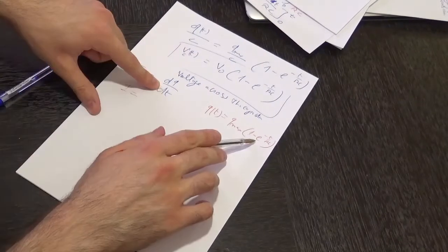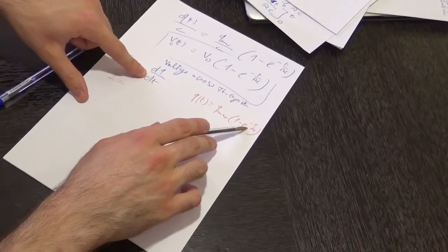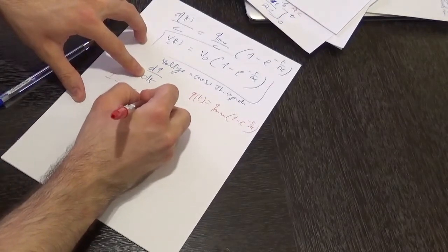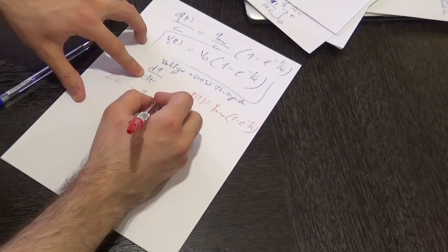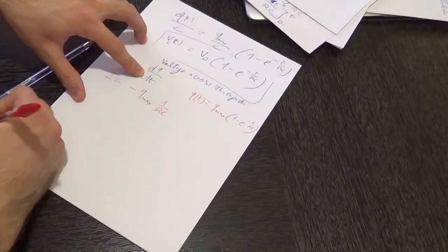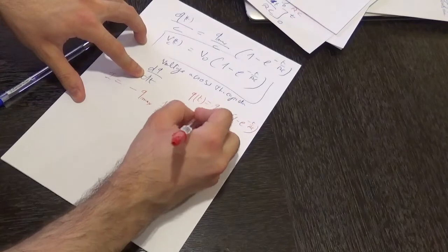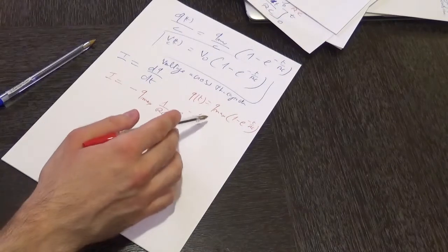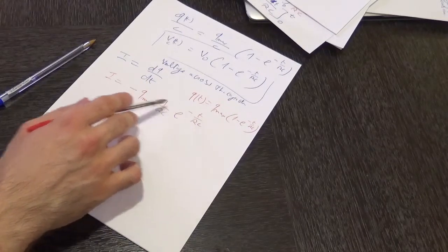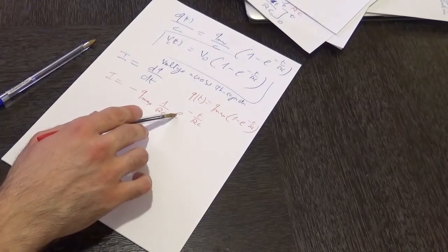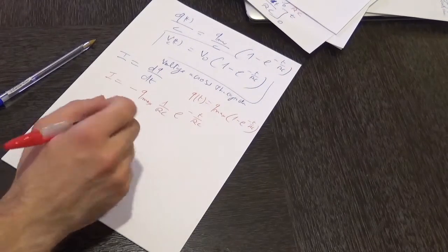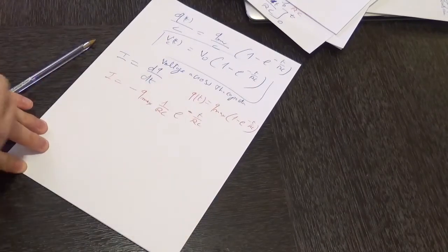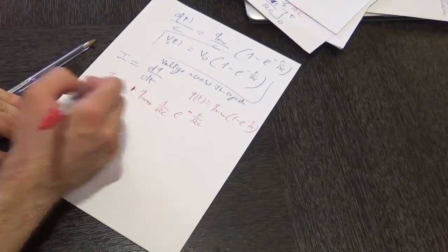So I is equal to, so over here we are basically differentiating that exponential which features time. So it becomes minus Q max times 1 over RC times exponential minus t over RC. Basically over here, t has the power 1, so there is nothing left from it but only the term which is multiplied by t, which is 1 over RC, and then we multiply it by that exponential minus t over RC. But we have forgotten to add also a minus sign, which is left from that derivation over here. So over here now we have a plus sign.